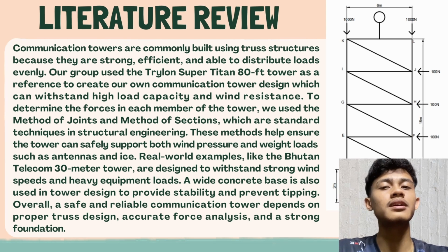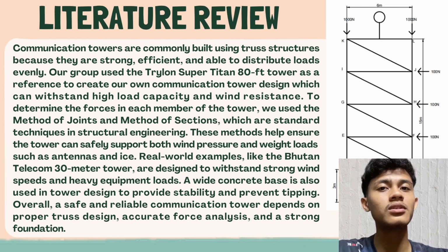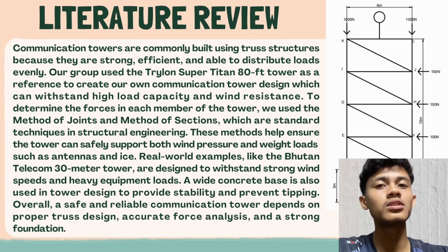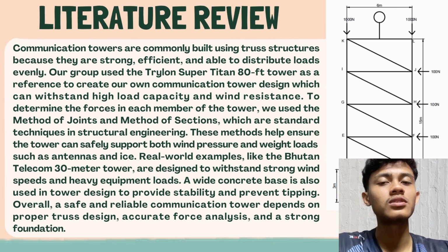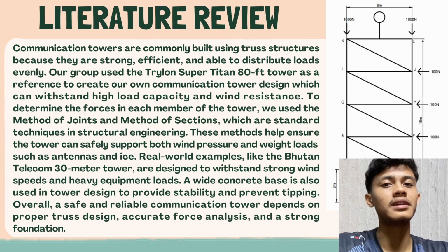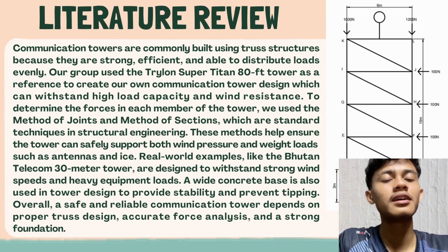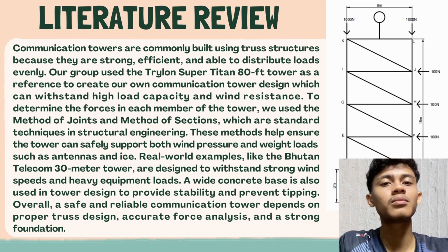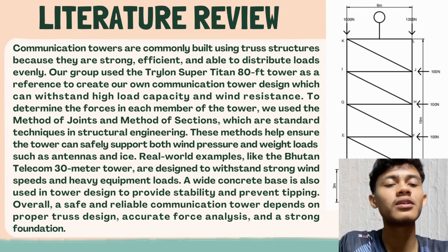These methods help ensure the tower can safely support both wind pressure and weight loads such as antennas and ice. Real-world examples like the Bhutan Telecom 30-meter tower are designed to withstand strong wind speeds and heavy equipment loads. A wide concrete base is also used in tower design to provide stability and prevent tipping. Overall, a safe and reliable communication tower depends on proper truss design, accurate force analysis, and a strong foundation.